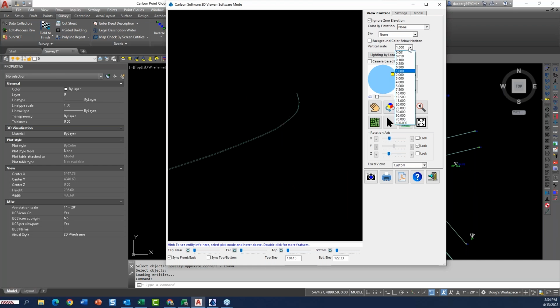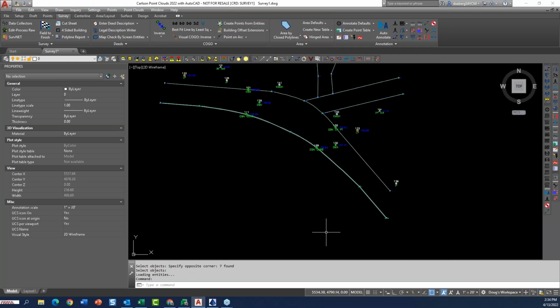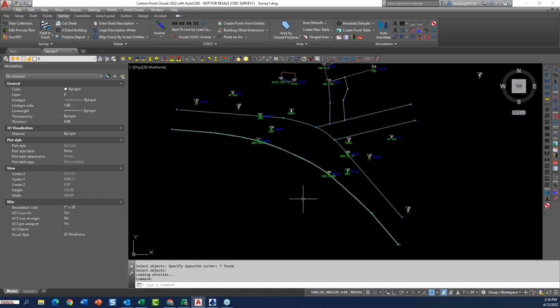And if I put on a vertical exaggeration scale, you can see how the curb height transitioned from the last shot down to this one. You can see it goes from half a foot down to 2/10 of a foot, and it could go back up, whatever. But again, I only had to code where it changed. So it remembers that first code. I call them sticky codes. They stick.